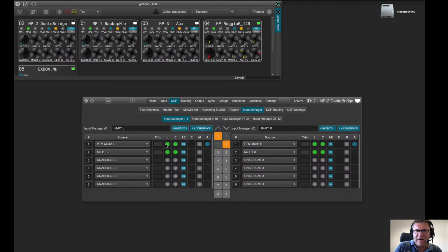But you might have the MADI carrier, and for some reason, the audio channels inside of that MADI feed are not there. And therefore, the coherence is reacting. This also allows you to have an analog feed as a main source, because the locking will never be lost on an analog input, but the audio coherence could be lost if there's no audio coming in that analog signal. And therefore, combining locking and audio coherence among several inputs will increase drastically the level of redundancy that you can offer.